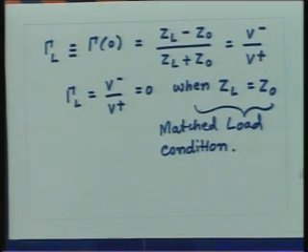One may then physically understand what is happening and why there is a reflection on the transmission line. Z0 represents some kind of a medium which is very smooth, on which the power is flowing along the transmission line. Suddenly it sees a disturbance on the transmission line in terms of impedance, because when it reaches the other end of the transmission line, the impedance is no more seen equal to the same smooth flowing impedance, which is Z0. So, it is some kind of a step change which the energy flow encounters, and because of that part of the energy tends to get reflected on the transmission line.